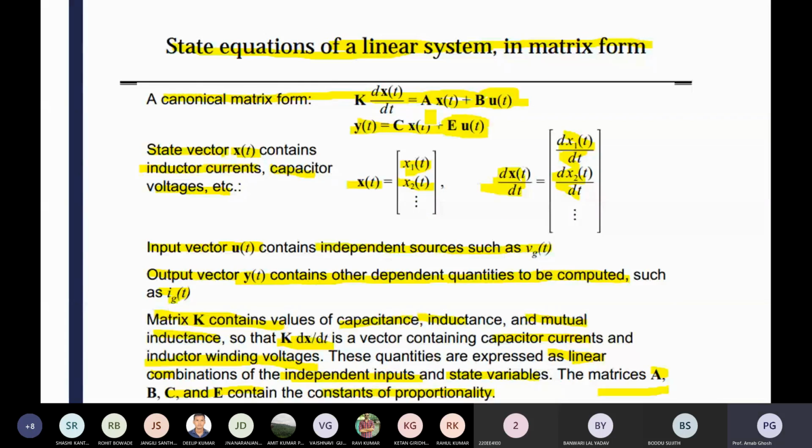So after writing all the differential equations, if you compare with this generalized equation, you can see that A is a matrix that contains different parameters like your duty, the inductor and capacitor values L and C, and the load resistance, of your switching converter. So if any of the parameters has changed, it has a direct reflection on the converter dynamics.